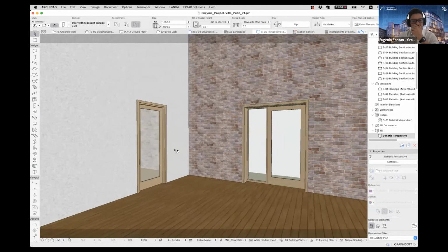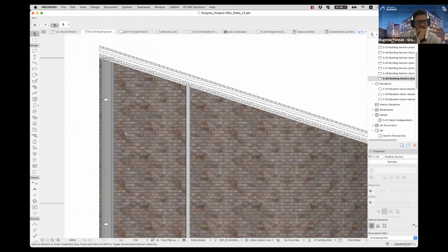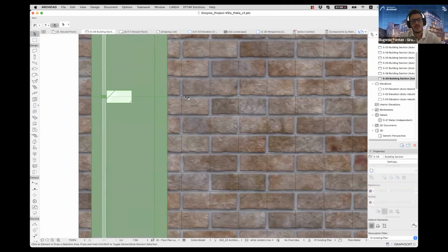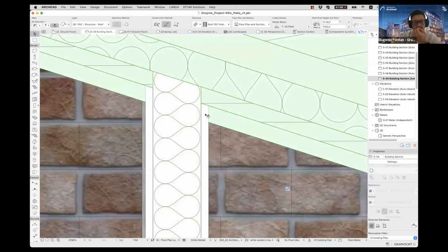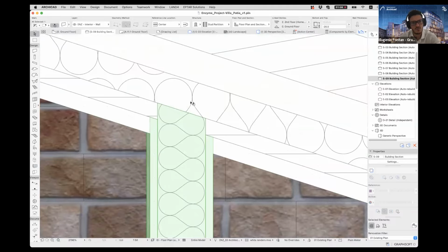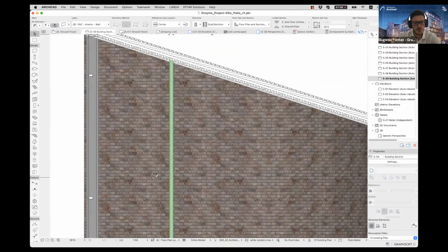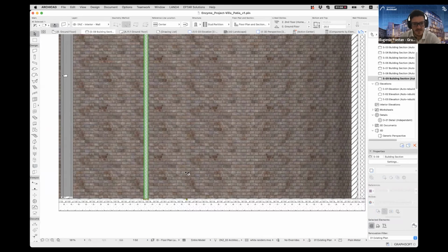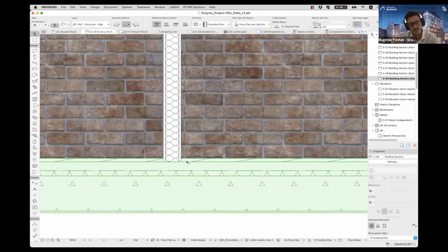And when we go to the section, this is how our section looks. This is the wall. It's cut. This is the partition. Look at the partition, how the different materials stop in different order, depending on the priority. This insulation has higher priority, so it's breaking these 1, 2 layers, stopping against the insulation of the roof. But also, it goes a bit below, and it also breaks the finish floor, because these partitions stand on top of the screed, and then the finished floor is placed after them.